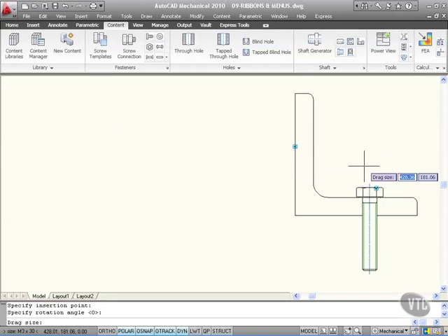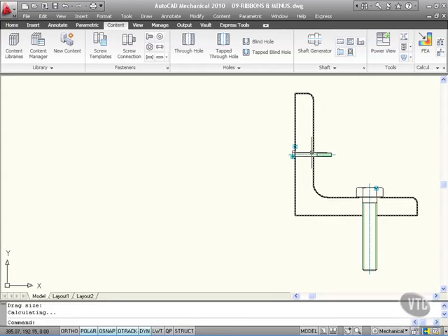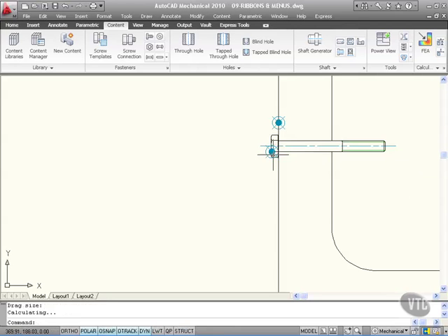And as you can see, there it is there. And I'll go for just a size there. As you can see, I can only go so far, because that particular family of bolts only go to a certain length. As soon as I click that, though, it's inserted again. And again, notice it's a dynamic block again. So I can click on it.